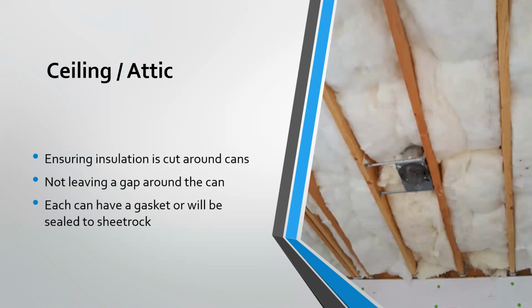So even when something is airtight, if you have temperature differentials of hot and cold, you will get air movement through the cavity. It's just called convective looping. Air will move up and down through the cavity, regardless of the fact that there's air entering or exiting that same cavity. It's just moving through the cavity due to convective looping.